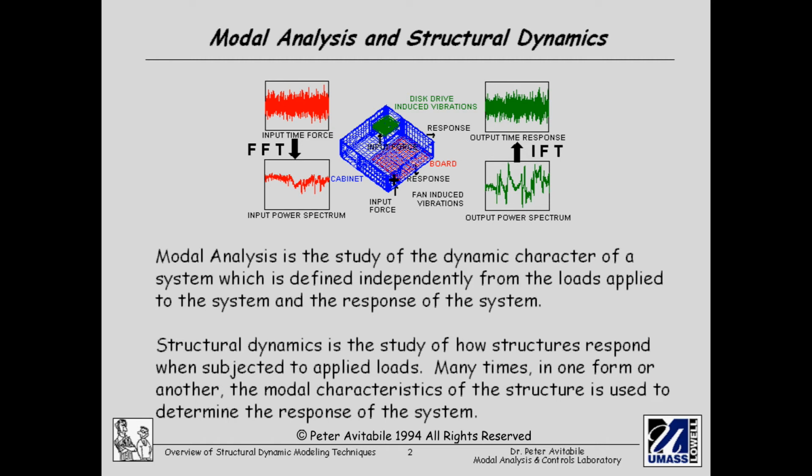So modal analysis is the process whereby we identify the dynamic characteristics, which are the frequency, damping, and mode shapes of the system. Now structural dynamics is the study of how structures are going to respond when there are loads applied on the system. What we find is in many of the solution schemes that we use to determine the response, in one form or another, the modal characteristics of the structure are used for the response calculation and are very important for understanding how the structure behaves the way it does.